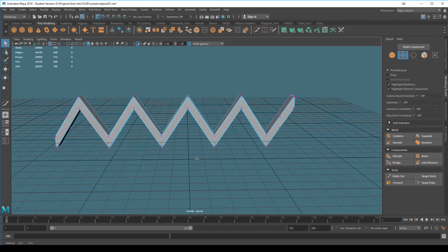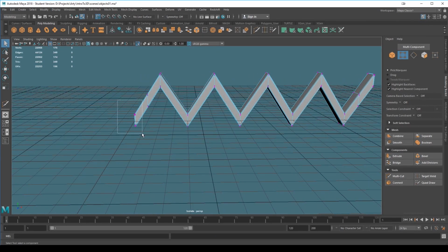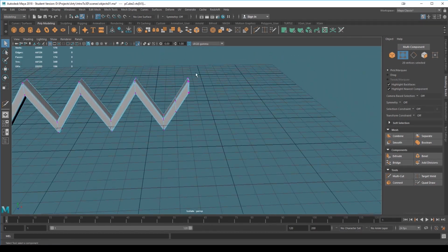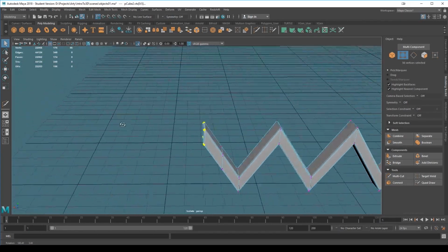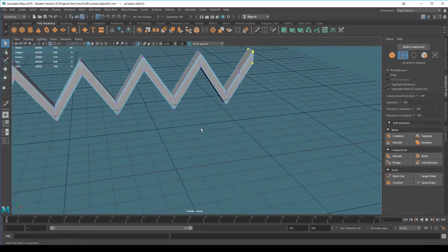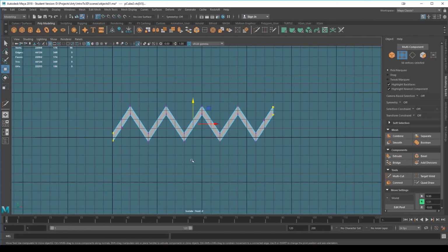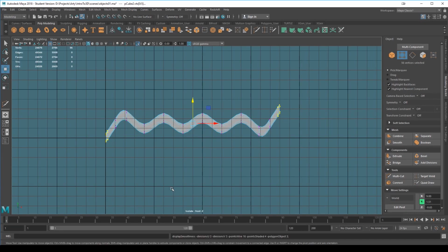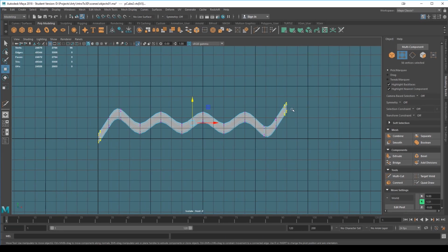So I'm just going to go into vertex, and I'll drag select carefully, just drag selecting this corner. And when I say carefully, I mean so that I don't accidentally grab any verts from up there. And same here, so holding down Shift, drag selecting these ones, just orbiting around, double checking I haven't selected something I didn't want to select. I'm going to jump to the front view, hit W, I'll turn off grid snapping, and I'll actually hit 3 and do this in smoothed mode.